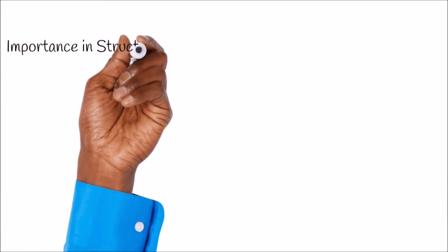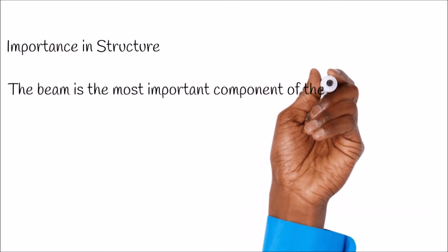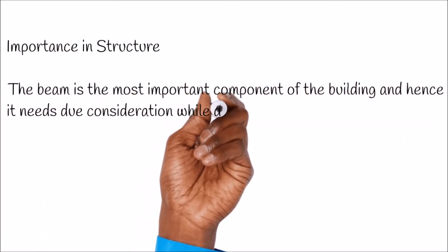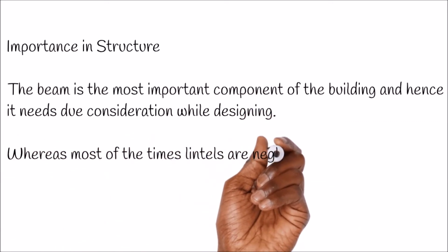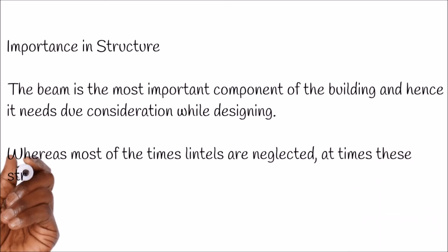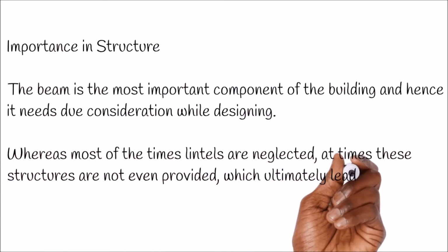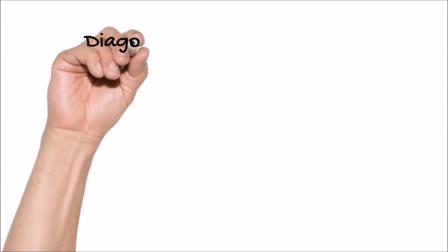Importance in structure: the beam is the most important component of the building and hence it needs due consideration while designing. Whereas most of the time lintels are neglected, at times these structures are not even provided, which ultimately leads to diagonal cracks at openings.